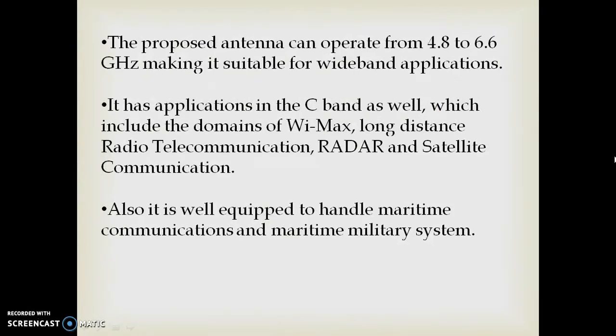It also resonates at 6.32 GHz. So the proposed antenna can operate from 4.8 to 6.6 GHz, making it suitable for wideband applications. It has applications in the C-band as well, which include the domains of WiMAX, long-distance radio telecommunication, radar, and satellite communication. Also, it is well equipped to handle maritime communications and maritime military systems.